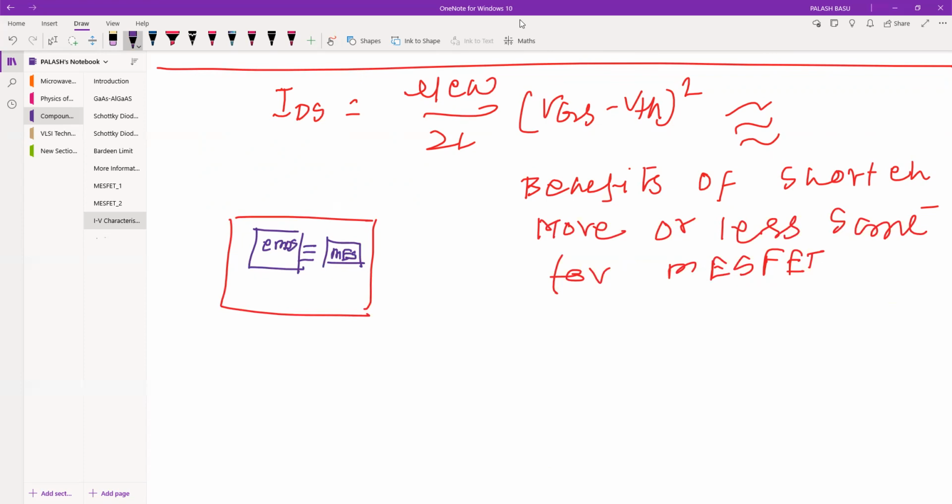So whatever MESFET output you are getting, whether it's modulation, demodulation, whatever, it is actually processed by the CMOS circuit, right? Now you know the CMOS is a very small transistor combination, and suppose the MESFET is very big. The beauty of having small CMOS on your PCB is gone, because ultimately your structure is very big.